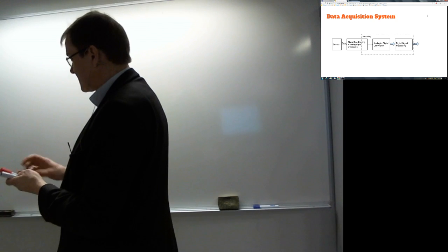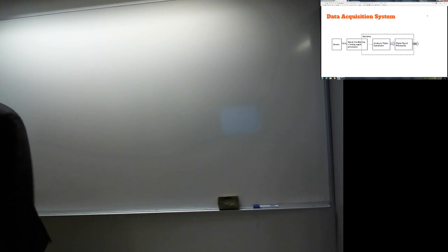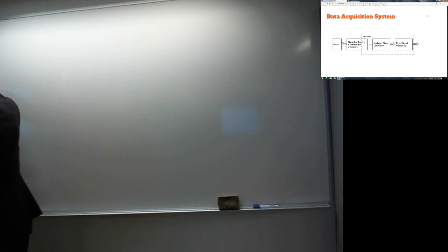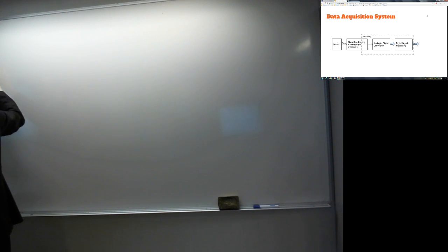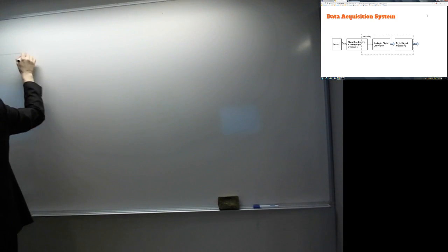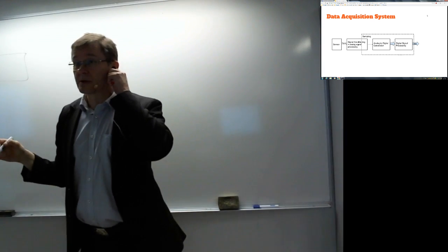Data acquisition, what is this all about? What we are talking about is right there on my slide: a system where we have a sensor that gives a primary signal, which has the transfer function to transfer the physical property into a signal. So this is just an electrical signal. After that you need to do something for it. That's basically analog processing, which is signal conditioning.